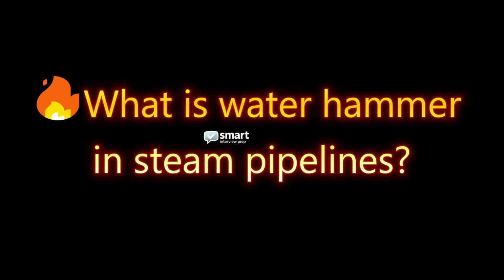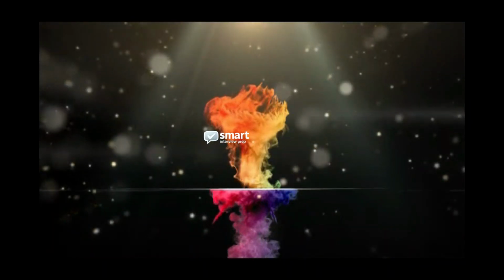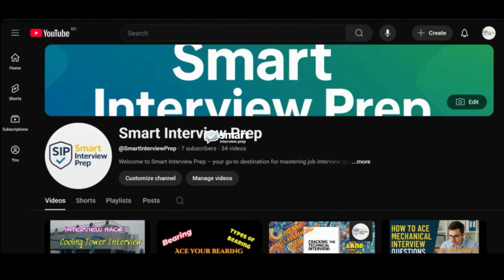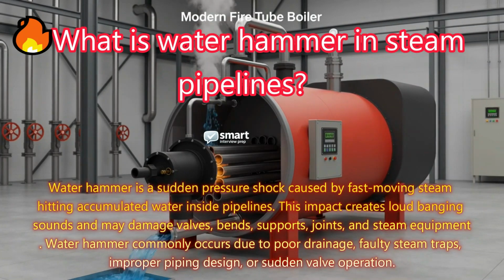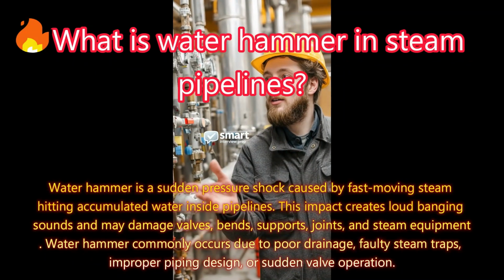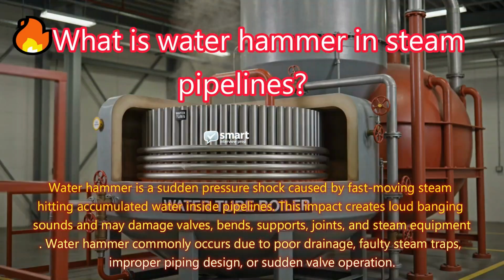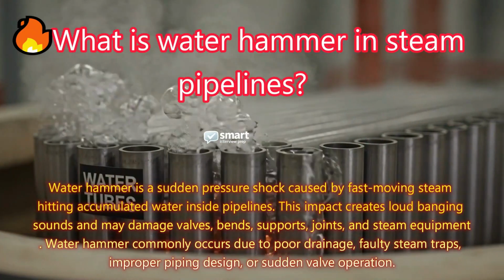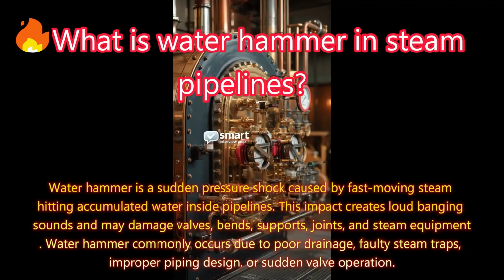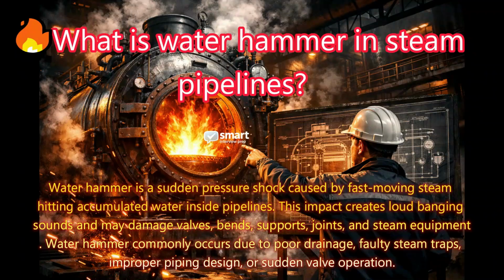What is water hammer in steam pipelines? Answer: water hammer is a sudden pressure shock caused by fast-moving steam hitting accumulated water inside pipelines. This impact creates loud banging sounds and may damage valves, bends, supports, joints, and steam equipment. Water hammer commonly occurs due to poor drainage, faulty steam traps, improper piping design, or sudden valve operation.